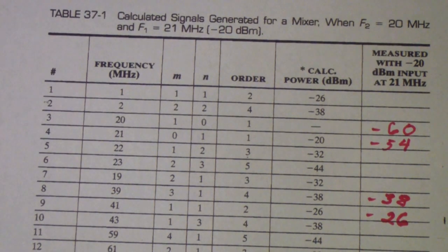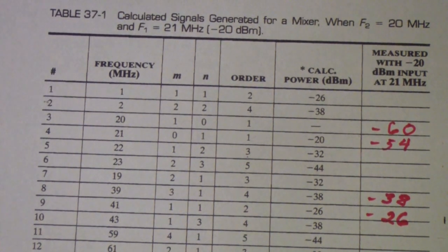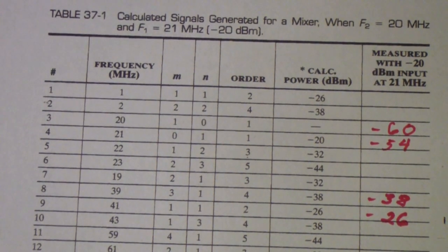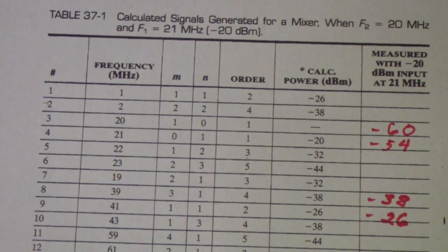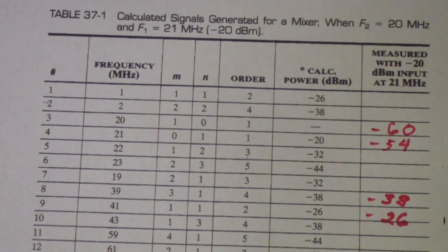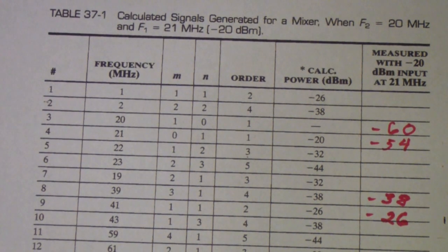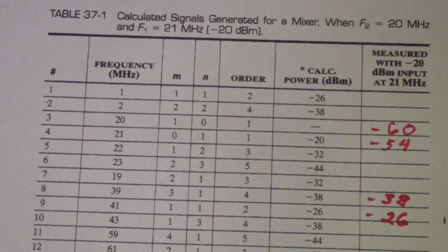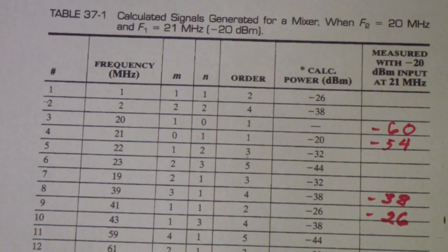But first, I want to raise the level of the local oscillator to the specified 7 dBm that MiniCircuits asks for. Now understand, what we've just done is the experiment that is shown in the Beasley and Miller lab handbook. But they operate at 5 dBm, partially because of the limitations of some of the test equipment in the labs at the time this experiment was put together. But we can go to 7 dBm, which is the MiniCircuits specified value, and then we will take those readings again and see if they change any.